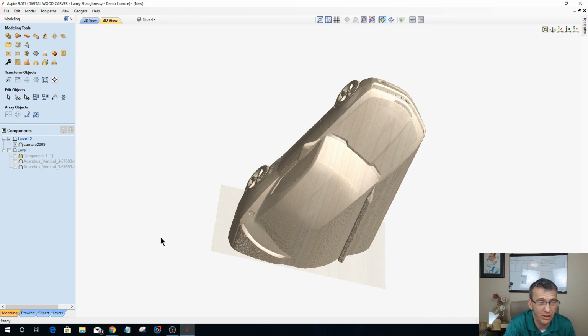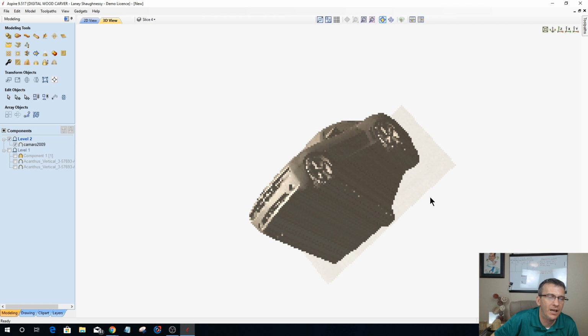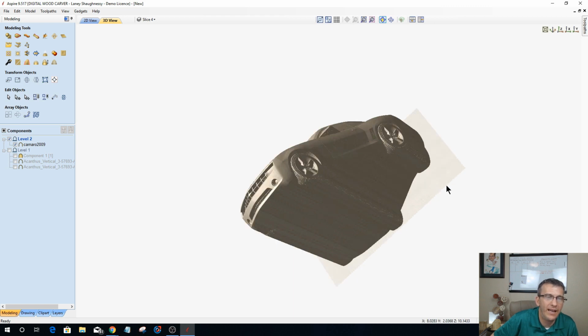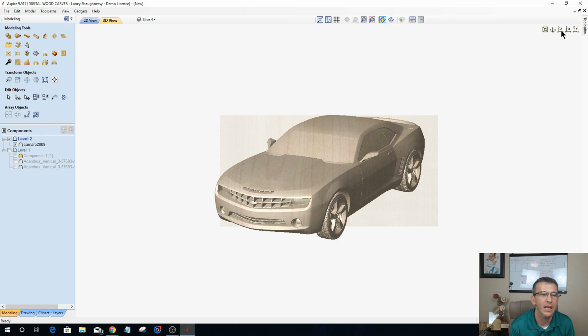And I'm not going to carve this like this. I'm literally going to flatten this thing out like a pancake, but I want to keep the surface detail. So what I have to do to emboss this model to make it a low relief carving, because right now it's not a low relief carving, is I need to create a duplicate of it. So I'm going to right click and duplicate it. The duplicate is going to be my base.